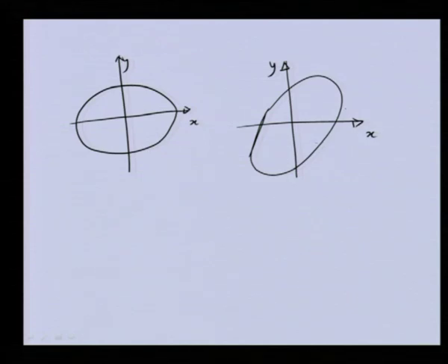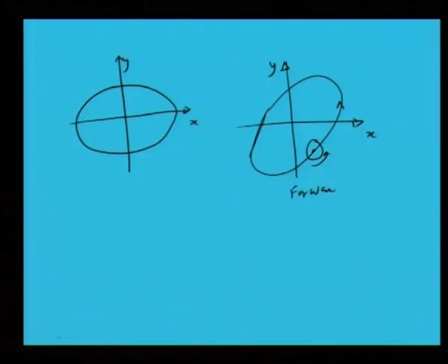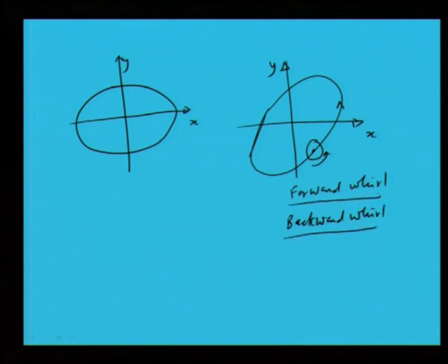So, now in this particular case also we will have a similar phenomenon. If we have a rotor center which is rotating clockwise or counterclockwise, the whirling will be in the same direction for forward whirl, but as we cross the critical speeds, this whirling direction will change. The spin speed will remain the same, but the whirl will change, and we will call that backward whirl. So, wherever there is a crossing of the speeds, the change in the whirl takes place.